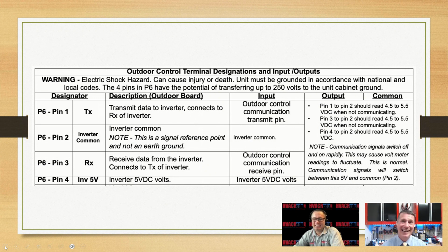I have people all the time say, but that control wire is great. It worked great for my old system. Now it doesn't work on this new crazy inverter. I want a new product. And I go, did you run new wire? No, I've never needed to run new wire. Did you check your wire? Well, how do I do that? Run new wire out the bedroom window. That's a quick way.